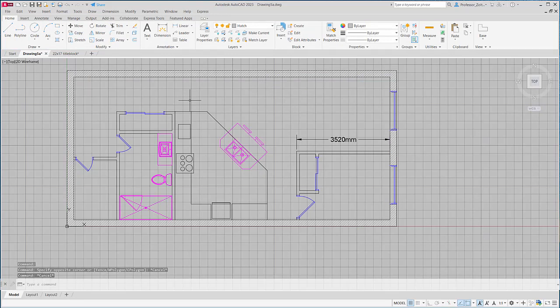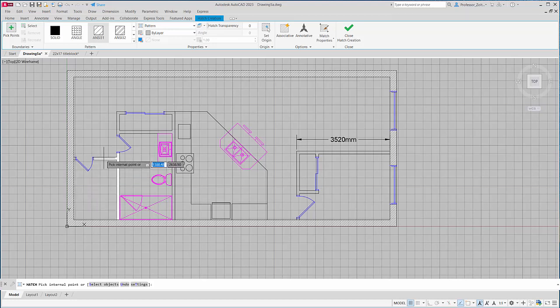Okay, so let's say, for instance, I've hatched this. And I want to hatch the walls with the same. Well, I can use the same command, hatch, and click on the different areas. But notice what it's doing. It's converting back to that very dense pattern. That's because every time we hatch, it goes back to that single value. So what else can we do instead?